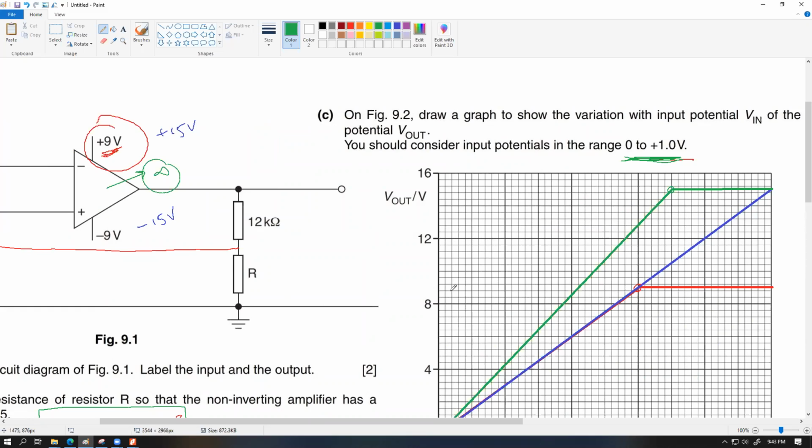Understand, sir. Beautiful. So we can even design a circuit which is highly resistant to saturation. Exactly. We can control the point up to which we want to avoid saturation by choosing these resistors properly, or we can choose the value of the supply voltages, or a pair of both of them, depending upon what kind of output we are expecting out of this circuit.